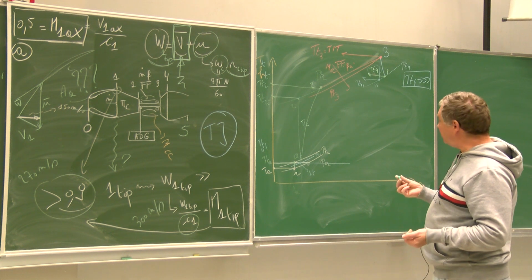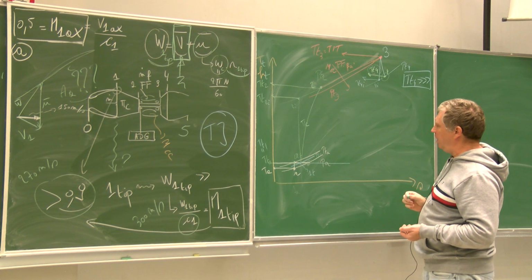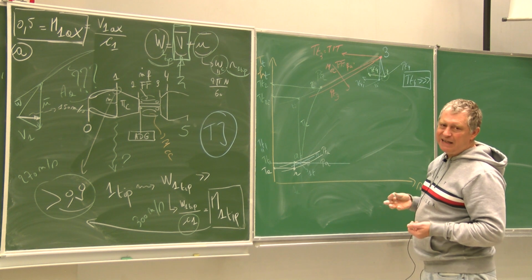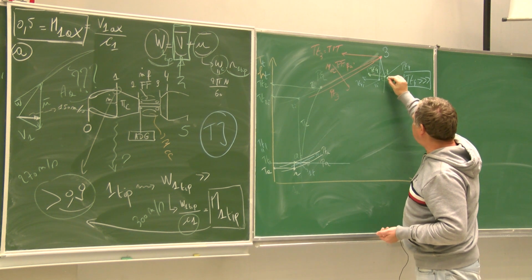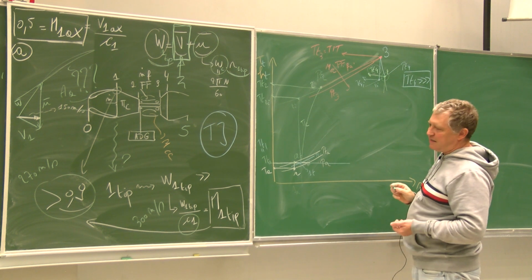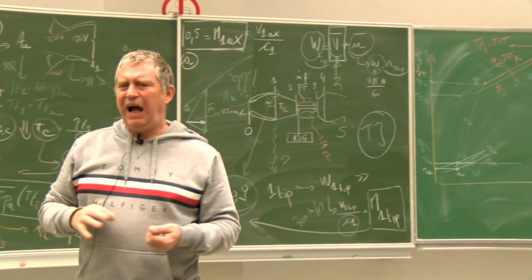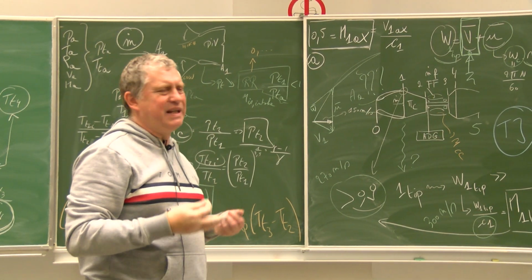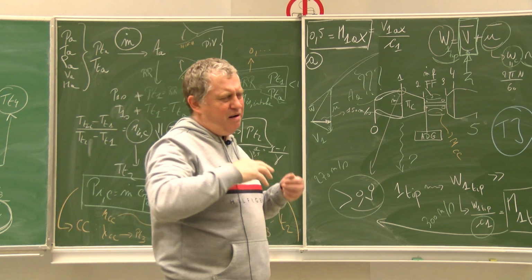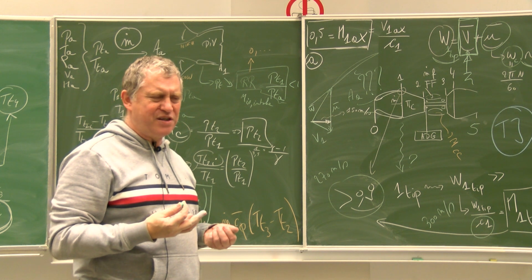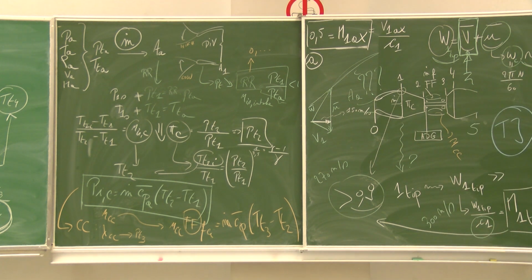And I'm entering from this point, this is from this point that I'm making the rationale, I'm entering here into the exhaust nozzle. The exhaust nozzle can be also isentropic or it can be non-isentropic. I will not make really the difference. I will consider the exhaust nozzle as isentropic, but I will not introduce an isentropic efficiency of the exhaust nozzle. This is a parameter that I will not really consider.